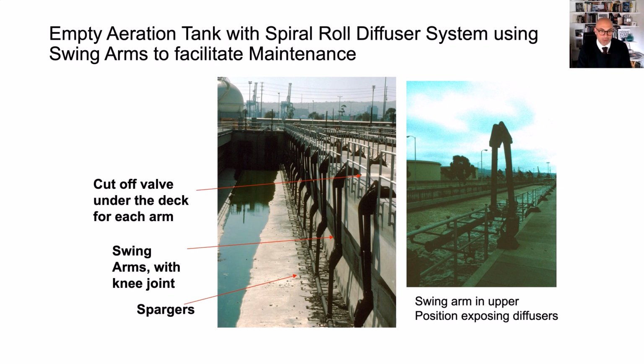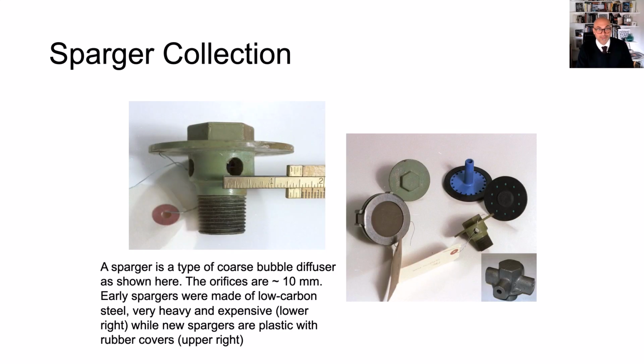However, remember one thing. When the diffusers are coarse bubbles, they require little pressure. So the blowers will need little discharge pressure. So once you want to replace them with fine pore diffusers, you either change the blowers or you are limited in your options because you are limited by the blower pressure. So you either have to put them above the floor by a lot or change to only, say, ceramic diffusers, which have the lowest pressure drop of all the fine bubble diffusers.